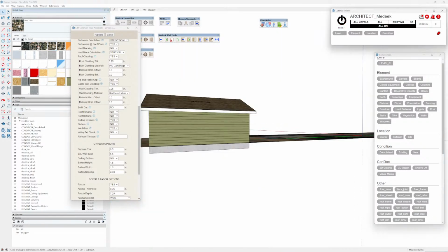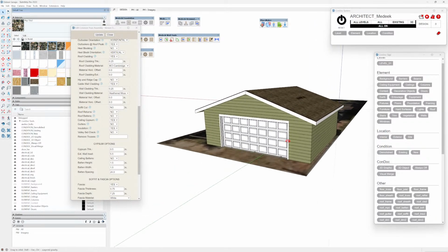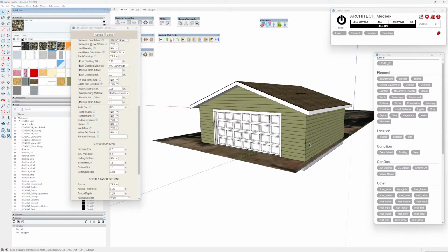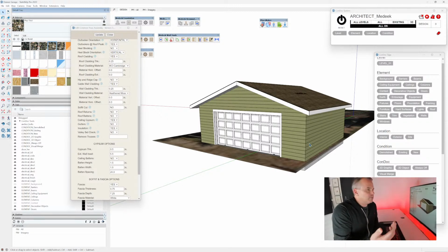I'll just hit reset. If you hit reset twice, it does a zoom extents, all right? And we've positioned our model at the origin, 0, 0, 0, that's our finished floor height. When I was setting up this project, I would have spent a little more time calculating the rear base plane elevation, which is the average between the back two corners of the site. On this project, I think it was a couple inches, so it really wasn't a critical thing, but you do need that calculated and represented on the drawings for Denver. But for this demo, it's easy enough to just call it flat.